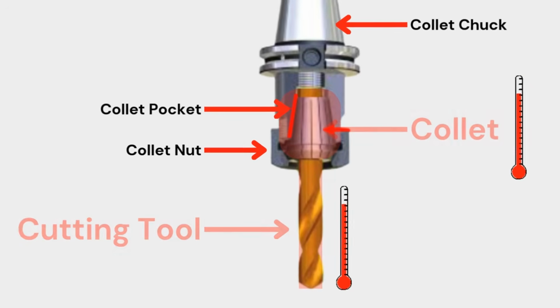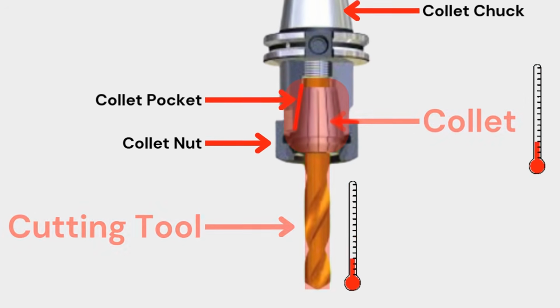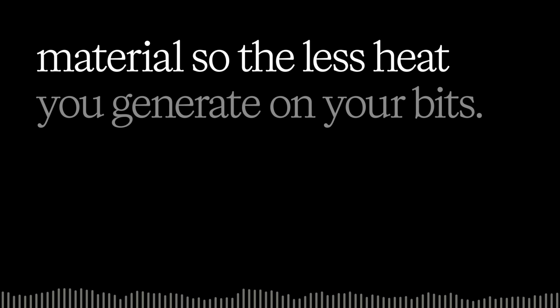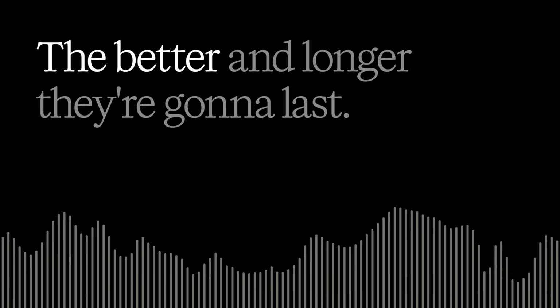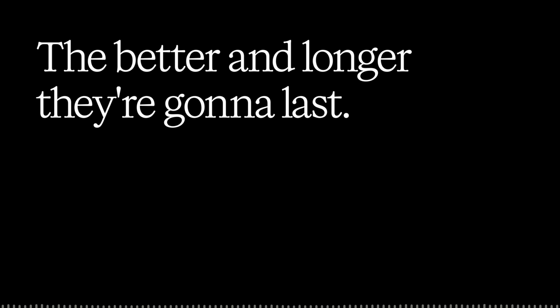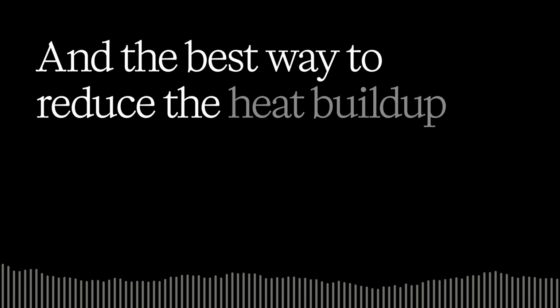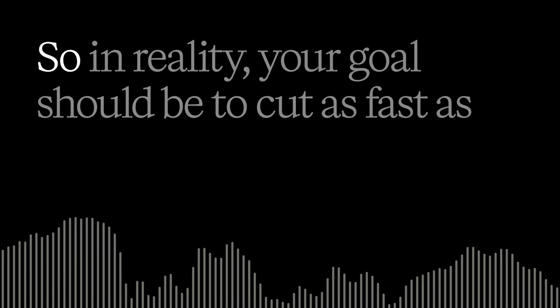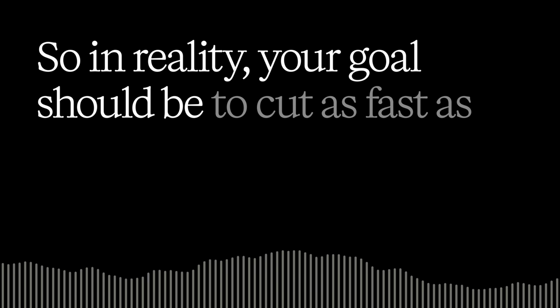Because of that heat getting cooled and heating and cooled and heating, it's going to really break down that material. So the less heat you generate on your bits, the better and longer they're going to last. And the best way to reduce the heat buildup on your bit is to run those toolpaths faster. So in reality, your goal should be to cut as fast as you can without causing issues or breaking bits.